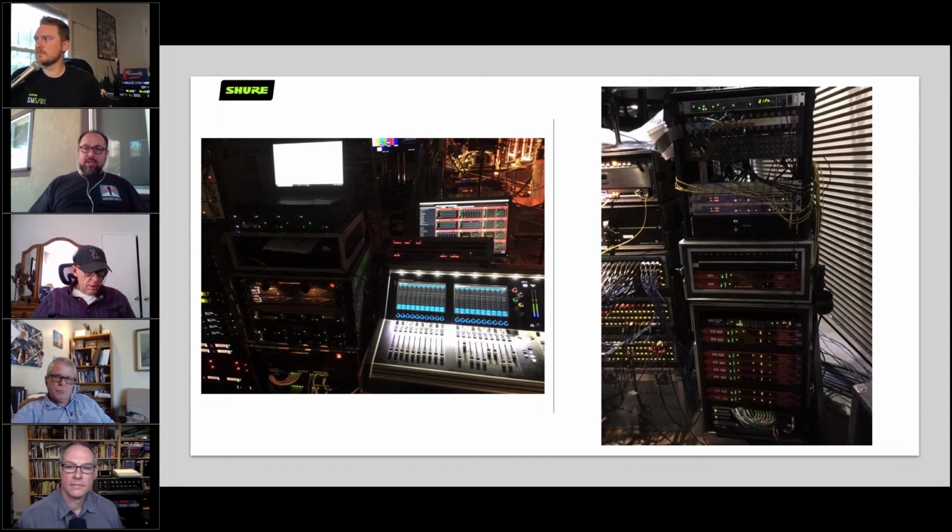And audio wise, if you've got W2 or whatever kind of analog system, or if you're using the Dante network, it's not a bad idea to go ahead and hook up the primary and secondary networks yourself and test it with your own Audinate program there, in shop, and make sure by the time your client or whoever gets the rack, it's just plug and play for them.